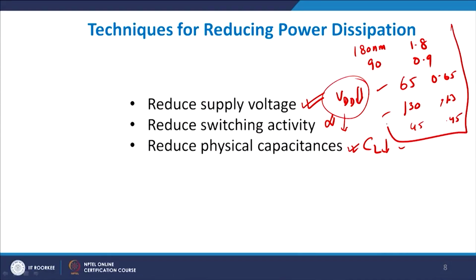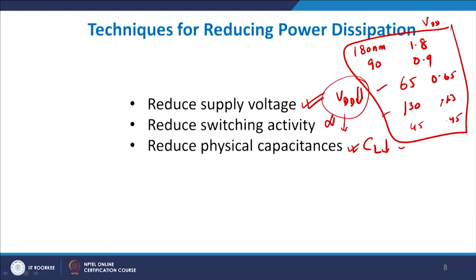This is typically a very layman sort of rough back of the envelope estimate, and you get these VDD values. So, the best way is to reduce VDD, but the price you pay for it is that you end up having a lower current and therefore a larger tau, and therefore the time taken will also be larger in this case.